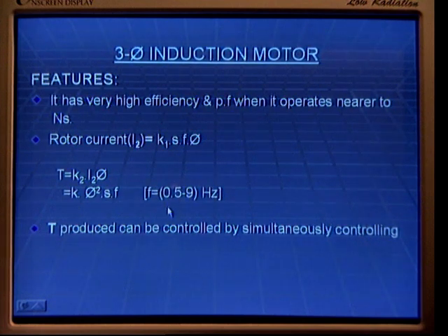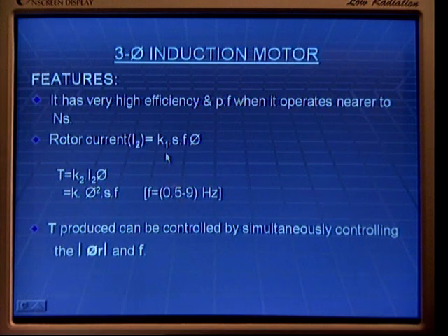If frequency is reduced, for the same constant torque required, then automatically we need to increase the magnitude of the rotating magnetic field, and the current in the same proportion. Here the frequency is reduced, the increase in the magnetic field is less in proportion, thereby the current is less. So we can get our required torque, and the current taken from the supply is the same.